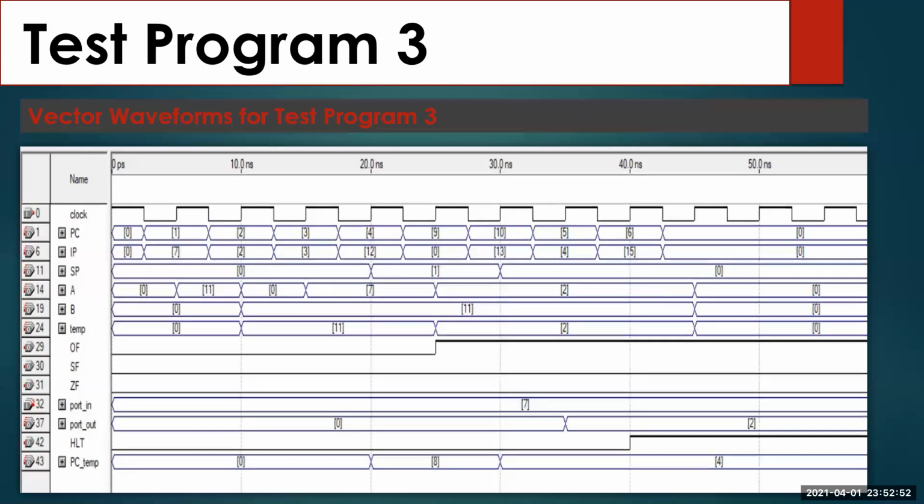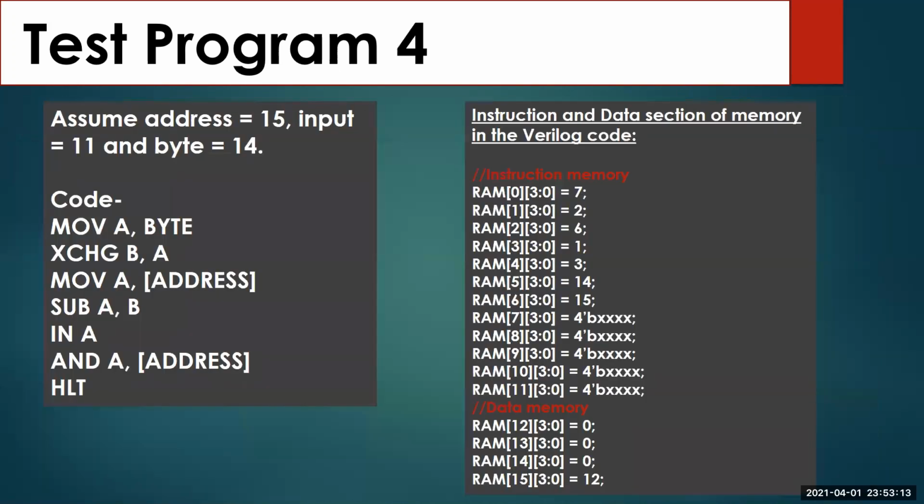When instruction pointer equals 0, add AB, 7 plus 11, is performed. As the result is greater than 15, we cannot store it in a 4-bit number, and hence the overflow flag is updated to 1. Return. When instruction pointer equals 13, the program counter is set to the value at the stack memory location at which the stack pointer is currently pointing, 4, and the stack pointer is decremented to 0 from 1.